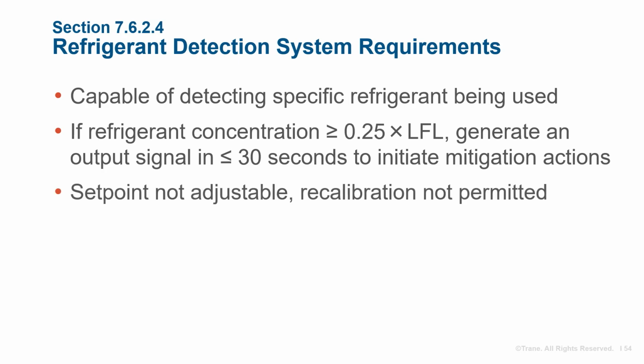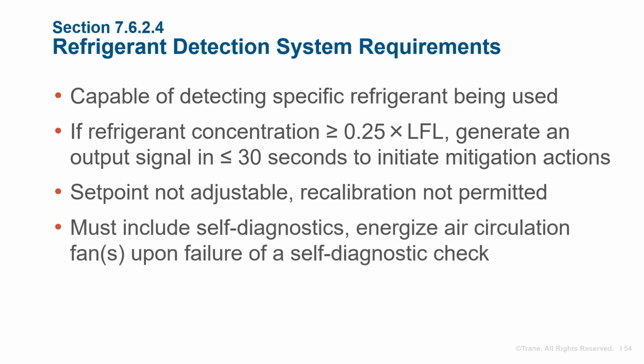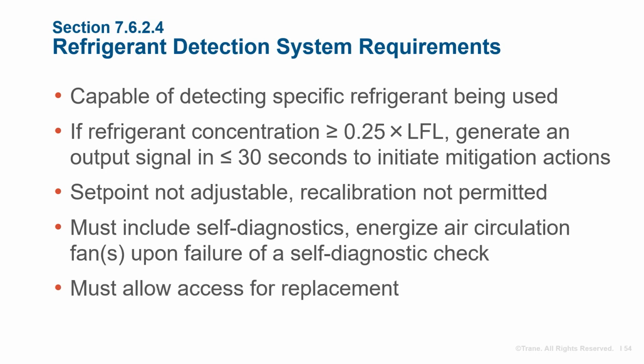These devices are required to be factory set and cannot be field adjusted or calibrated. This prevents unauthorized adjustments. The detector must also include self-diagnostics, and if it fails a test, the equipment must energize its air circulation fan. Finally, the device must be modular and accessible for replacement.